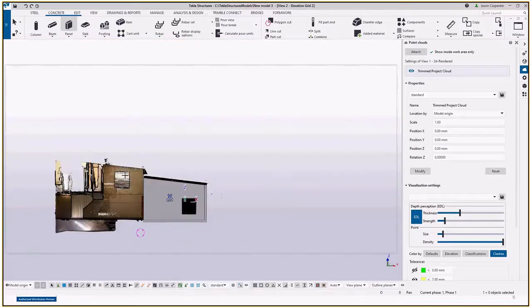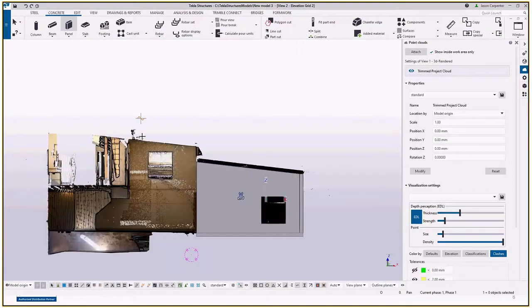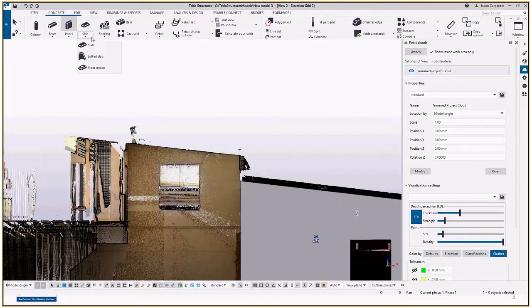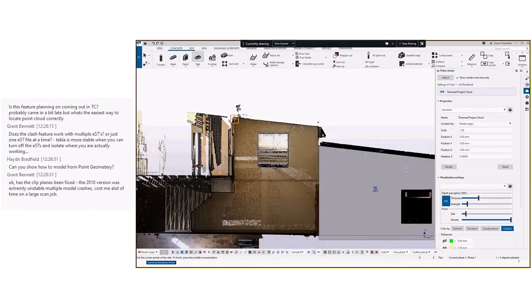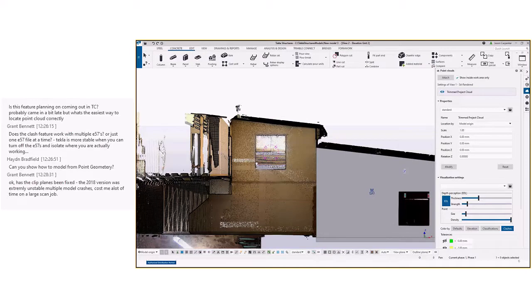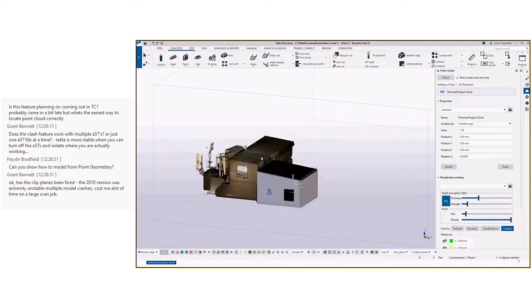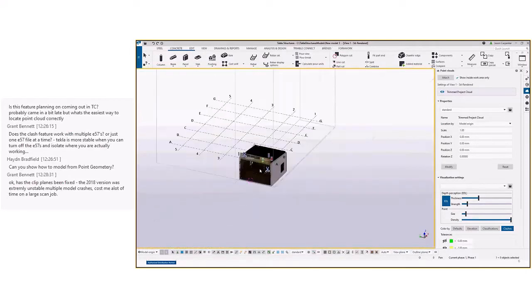So what I'll do is actually go to a plan. This is a plan view, but let's go a bit of drafting license here, and we're going to actually create a slab. So we can actually create a slab in this face here by selecting points. Now obviously we have to go through and refine these in the future, but essentially that would create a slab based on where that is. Now if we were to go through and go into here, I'm just going to delete a couple of reference planes.